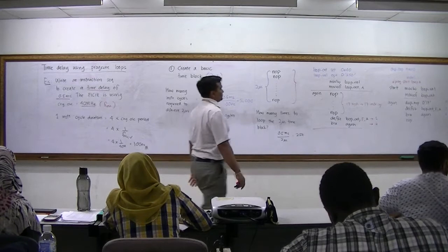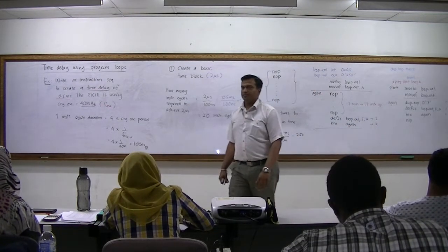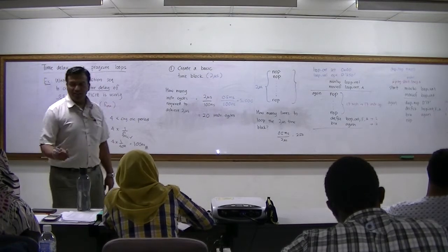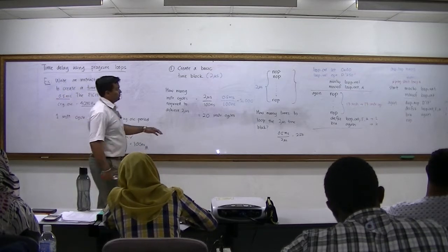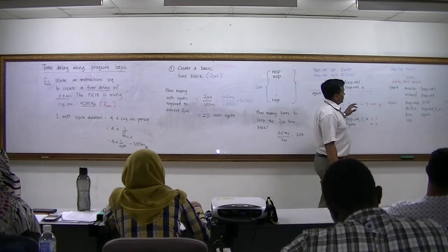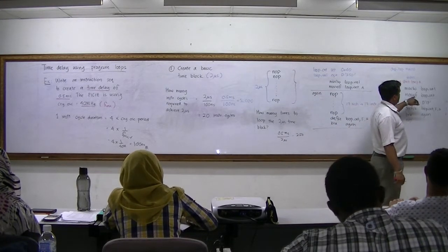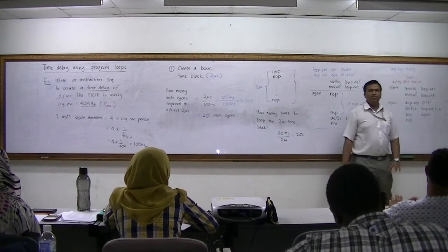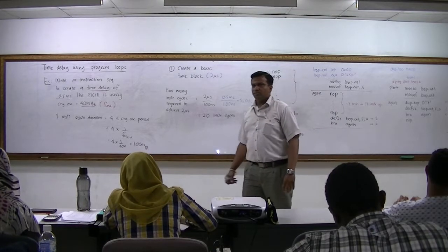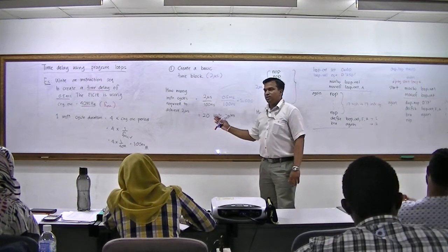Okay. Is that okay up to this one? Yes. So is there a limit to how many times the counter can loop? That's what I wanted to say. Like now when we calculate 5,000 cycles, with one loop you cannot do 5,000 because the maximum that you can actually pass over as the loop count is 255. So we will see this in the next example. Now, are you all clear with this?